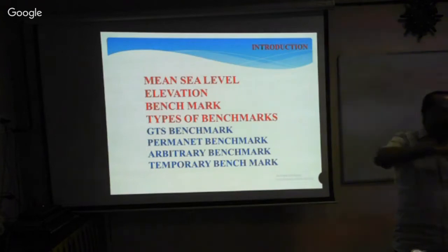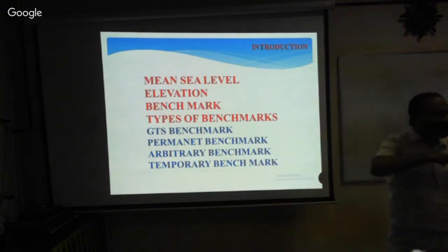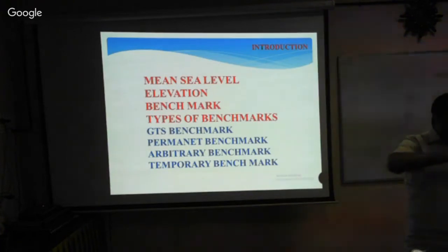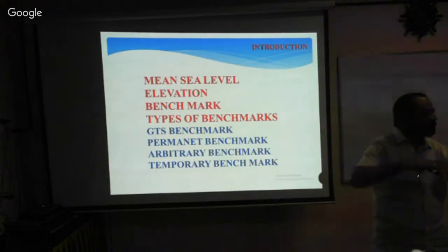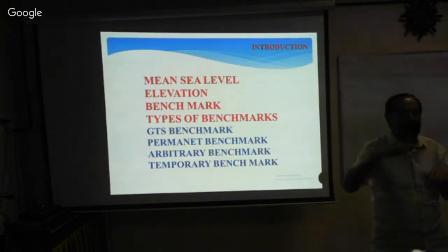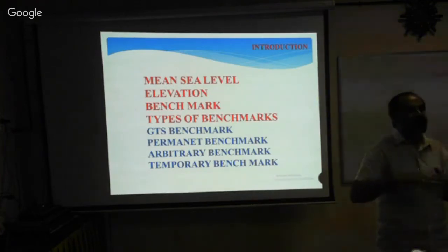That is the benchmark. Benchmark means a reference point of known elevation. Now please tell me what is the elevation of the seashore, the MSL? That is the reference point of known elevation, known height, known value. What is the value of the MSL? The value of the MSL is 0 meters, 0.000 meters. Understood? That is the reference point we have taken.